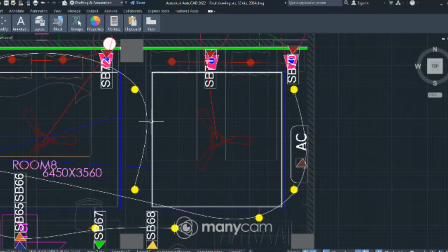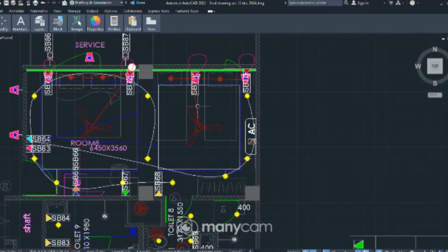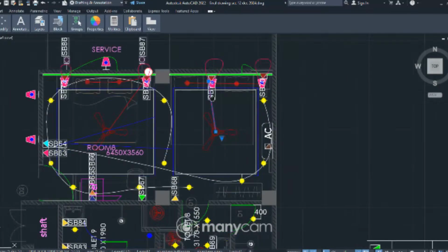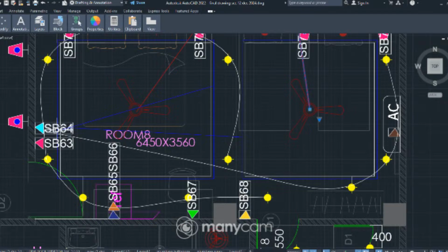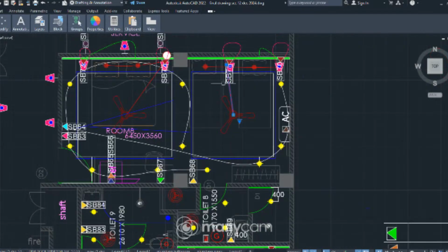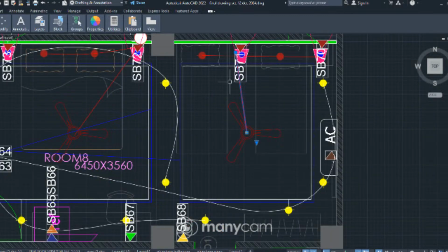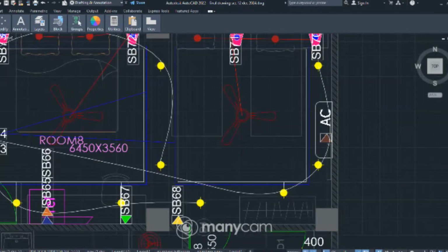But it depends on the areas. If you go to any other place, there the people want light, or they create issues. So you have to give panel lights there so that they feel there is more lighting in the rooms, more ambient light, if people are not used to those dim lights. For people who just want accent lighting, they can just switch on the COB lights and bed lights. That will give enough accent lighting to them for relaxing.